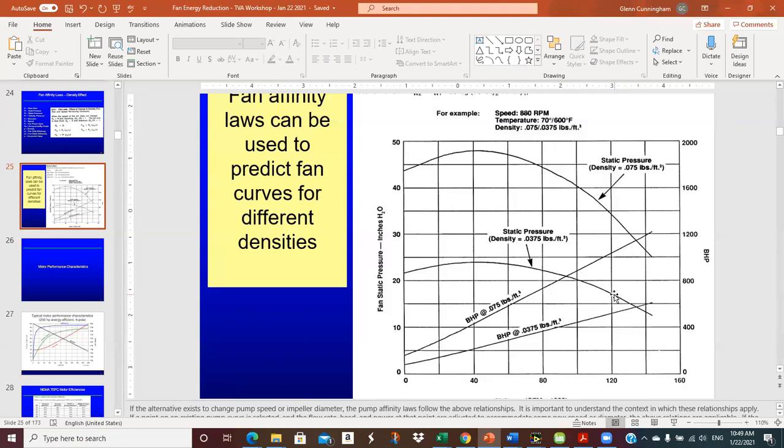There's a recommended number of diameters, 8 to 10 diameters upstream and 4 or 5 diameters downstream of straight duct, something like that. I would find the longest straight run you can and get kind of in the middle of it. You want more upstream than downstream. That will smooth out the velocity profile and make your measurements better.